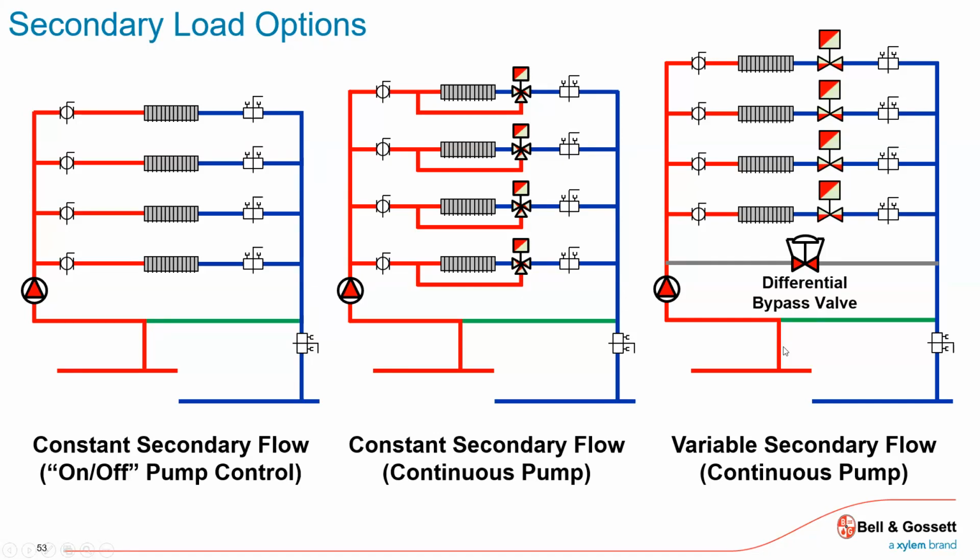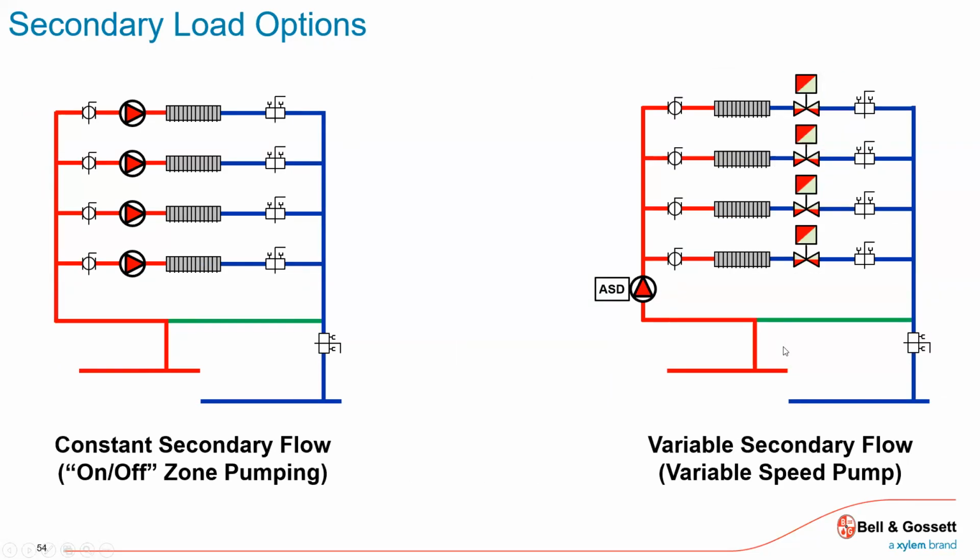And I've got this primary main, this primary return, and I'm connected through this common pipe. This green pipe is my low pressure drop, my common. And you notice it's not showing these little closely spaced T's because when you get into the real world, there's going to be some separation. Just remember that 1.5 feet of head loss, whether you're dealing with 3/4 inch pipe or 16-inch pipe. If I can keep that pressure drop very low, I've achieved my decoupling. And again, they're just showing some examples.